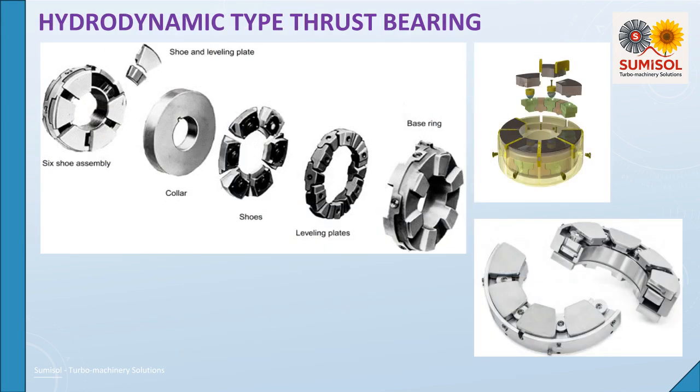The exploded view of a typical hydrodynamic thrust bearing is shown. Each bearing consists of a series of pads supported in a carrier ring, retainer. Each pad is free to tilt, resulting in a self-forming hydrodynamic film. The self-equalizing design balances the load between the pads and accommodates misalignment or deflection between the bearing and collar. The carrier ring may be in one piece or in halves, and the size and number of pads are selected to suit the operating conditions.